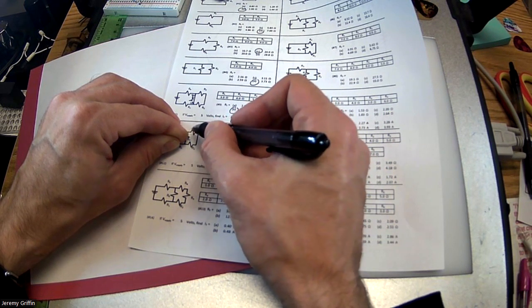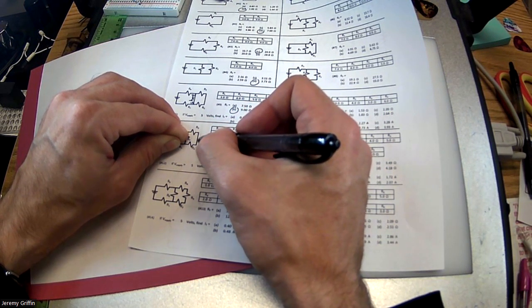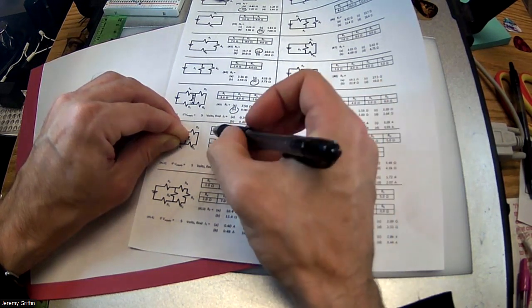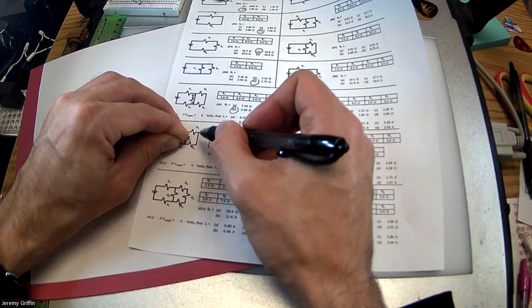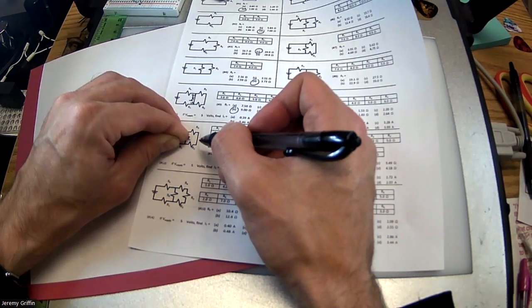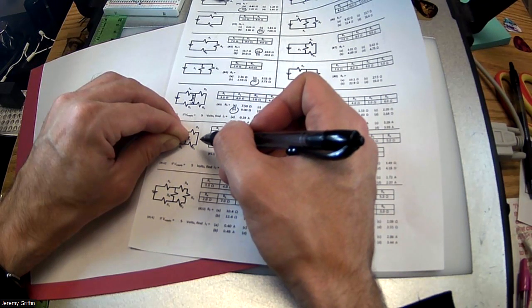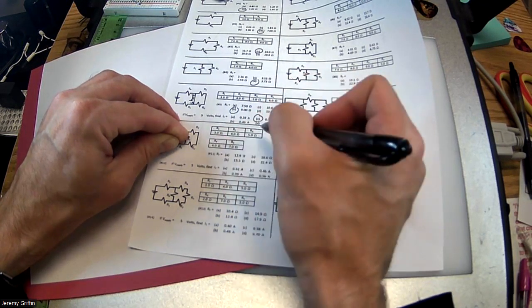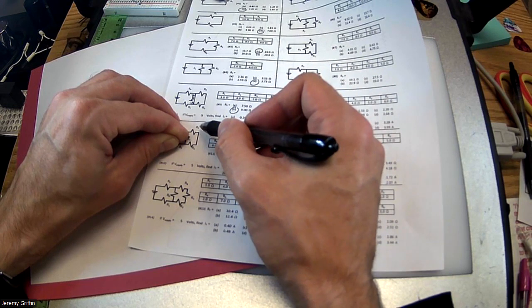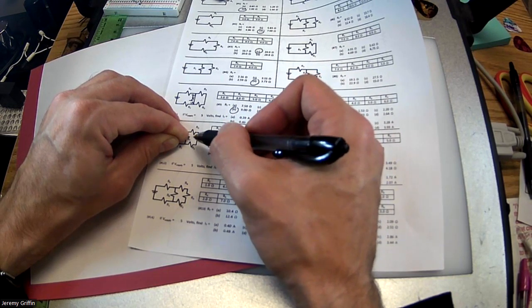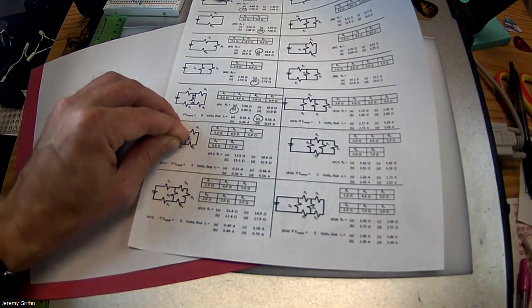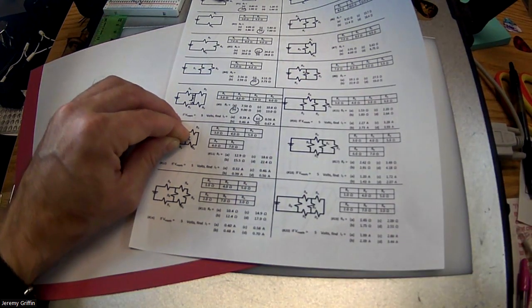All the current has to go through this one, and then that current has to go through this one. And if it's series, do you just add them, or do you treat it like two guys painting a fence? Just add them up. So I got 4 ohms there, and I got 5 ohms there. So for me, 4 and 5 is 9 ohms. That's 9 ohms right there. You guys figure out your equivalent resistance just in that part of the circuit?